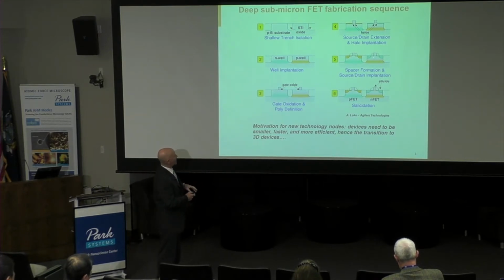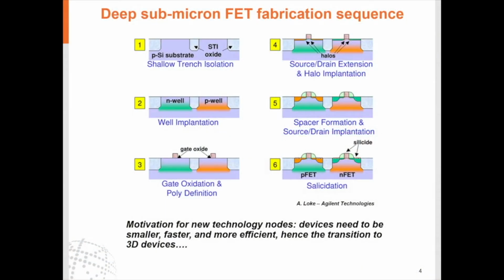So for our N-channel device, we're sitting in P-type silicon, and we're going to implant arsenic and phosphorus over here. Conversely, for our P-channel device, we're sitting in arsenic and phosphorus-doped silicon, and then we're going to put boron in there, such that on one polarity we have an NPN device and the other PNP. Then, in order to turn the device on and off, we're just going to apply a charge on the polysilicon gate there and essentially turn one switch on and one switch off.